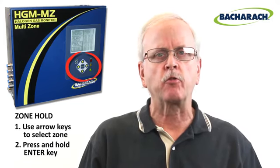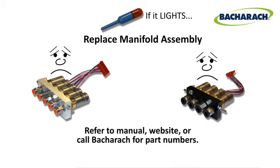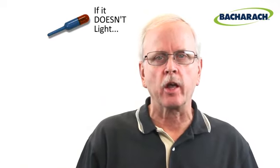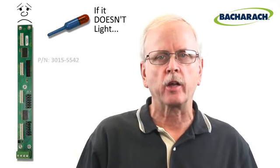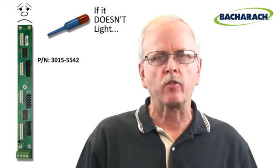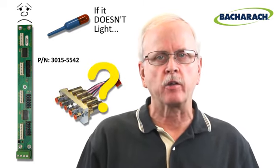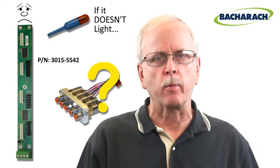Next, you can use a magnetic field detector held above the suspect solenoid to verify that the solenoid control board is telling the solenoid to energize. If the magnetic field detector lights, you know that the solenoid circuit board is functioning and the problem is a mechanical issue with the manifold assembly. It will likely need to be replaced. If the magnetic field detector does not light, you can assume that the problem is likely electrical and associated with the solenoid printed circuit board. In this case, you may also have a mechanical problem with the manifold, but really have no easy way to test that in the field if the solenoid PCB is compromised.